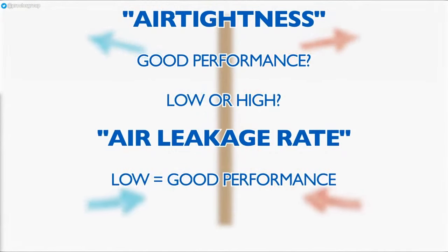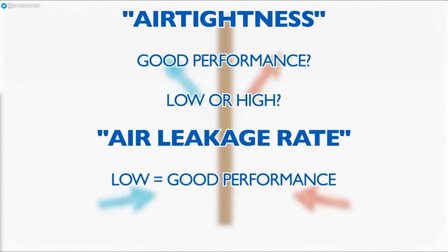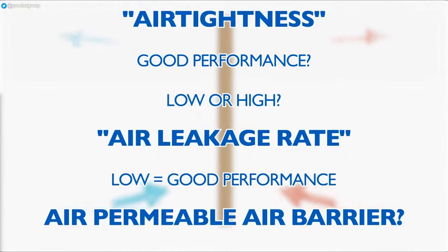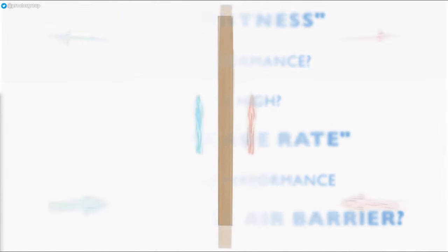When we talk about an air tightness of 3, for example, this is the figure we mean, so to avoid confusion it's preferable to refer to an air leakage rate of 3. To further complicate the issue, air permeability is the figure used to express air barrier performance. In most cases, an air barrier membrane will be 0, or as close to 0 as to not matter, so this should not be taken to imply any effect on the air leakage performance of the building as a whole.